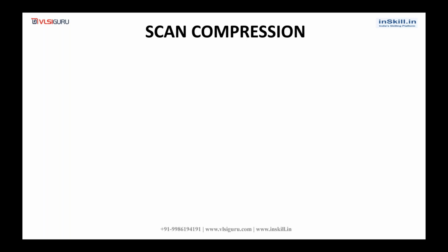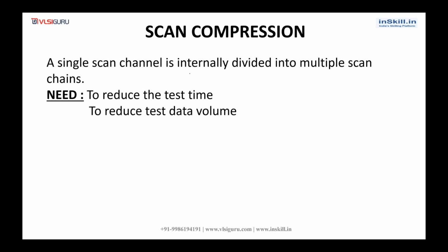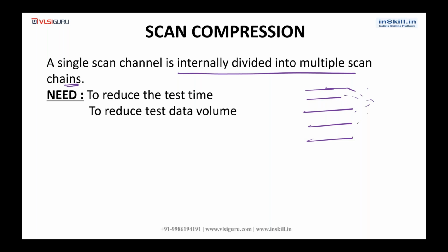Next is scan compression, which is also called EDT insertion. A single scan channel is internally divided into multiple scan chains, or you can say the internal chains are compressed into external channels. This is nothing but your external channel.